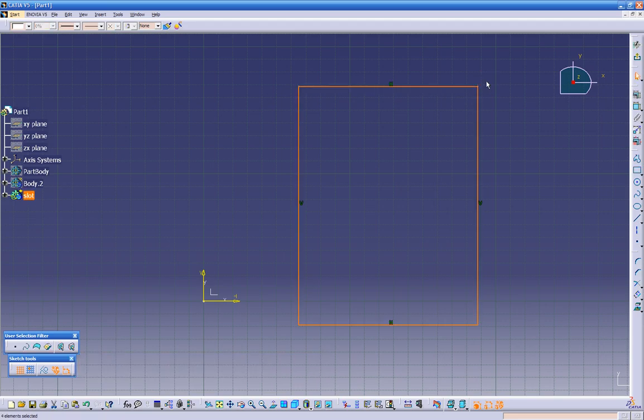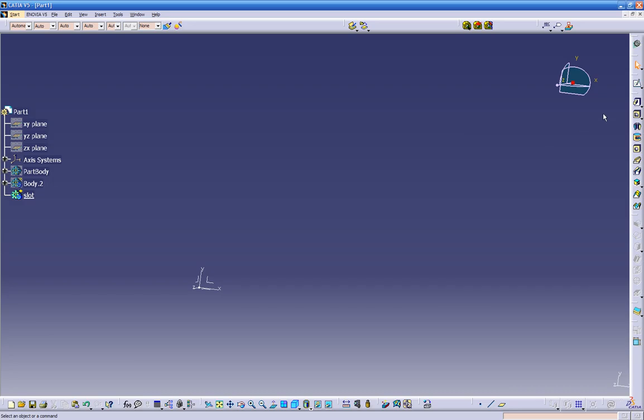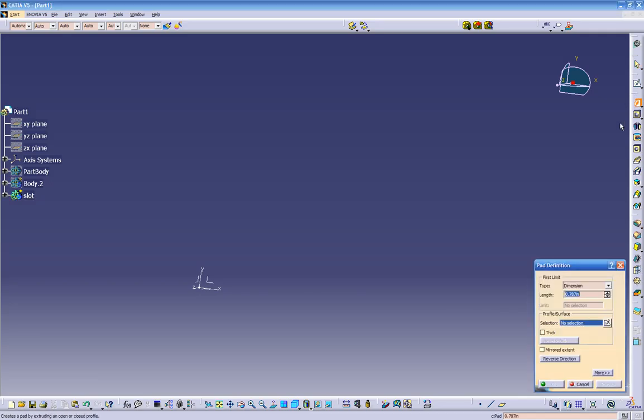Before I do this, I want to show something else. We can create a rectangle pad without doing the sketch separately, straight from the pad icon. So let's cancel that, get out of here. Instead of going here, clicking, coming over here, creating a rectangle, and opening a sketch, there are a couple of steps, but we can just click straight on the pad.